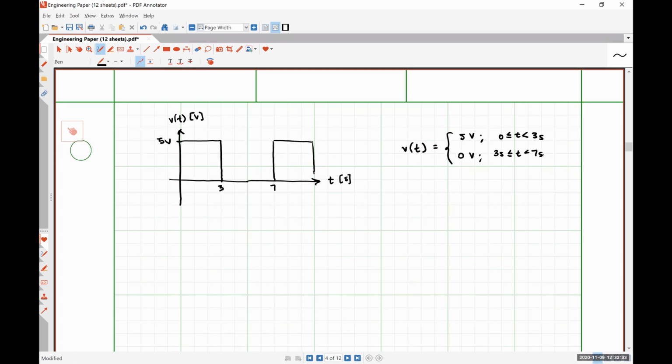How would I go about finding the effective value of this periodic series of rectangular pulses? Would you take the integral? So V effective, there is absolutely something relating to the integral, yeah. So I'm going to put an integration sign here. What do you think the limits of my integration should be? If you watch the video, you would know what they should be, but this is a periodic function, right? So we're going to integrate over exactly one period.